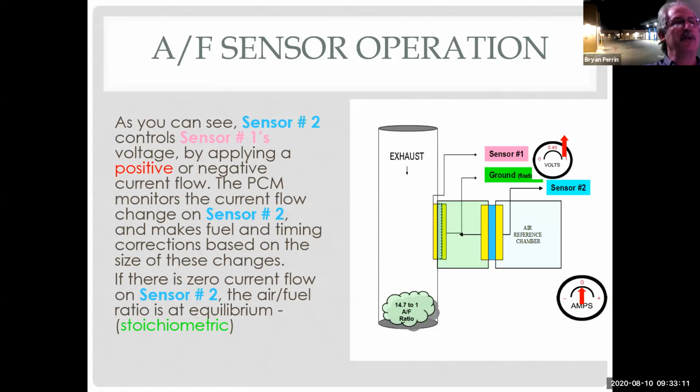So they run them really more like a diesel, where we're controlling the fuel going in, and we're concerned about balance, and we're concerned about compensating for altitude and load, but we're not really concerned about stoichiometry. That's why when they gun a jet, you see all that black smoke out the tailpipe. That's rich.